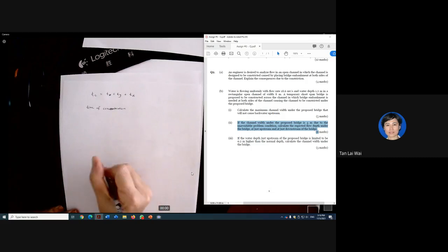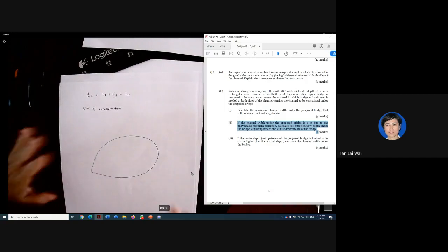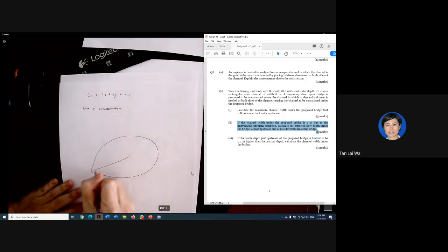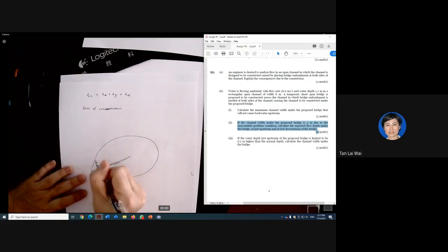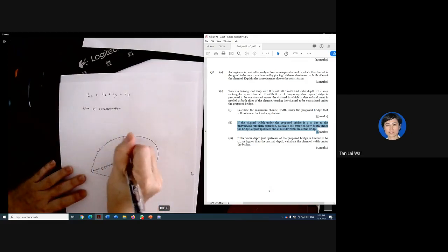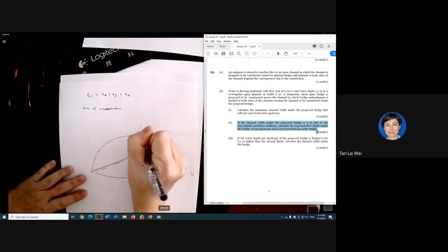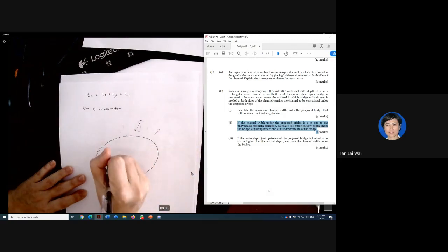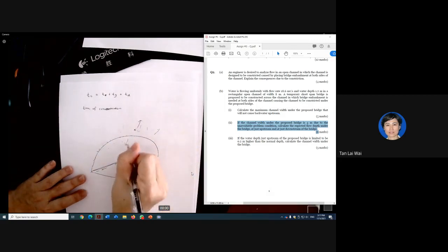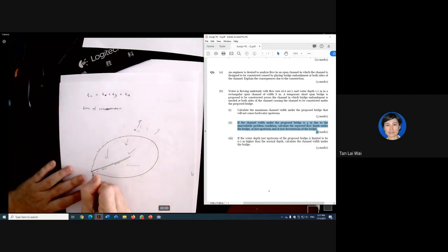I'm going to draw a simple catchment. So this catchment, there's a river, it will flow downward. I already determined that this is the highest point, that means when rain drops on this plan view, whenever rain drops at this area, it will flow elsewhere, but whenever rain drops within this area, it will eventually end up at this lowest point.